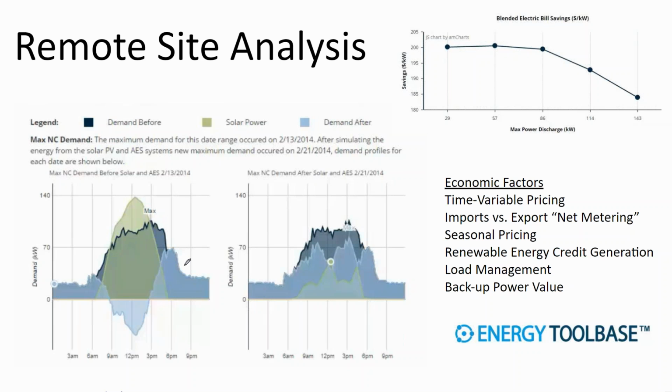So then we need to go and add a model where we say, okay, I'm going to go for this target threshold of demand. So this is showing me a 70 kilowatt demand. I'm going to aim for a 51 kilowatt threshold. And so whenever my new building demand is above this certain threshold, I'm going to turn on my battery to reduce that threshold. And then if I'm charging my battery with my solar array, I need to make sure that my solar production is equivalent to my battery production.